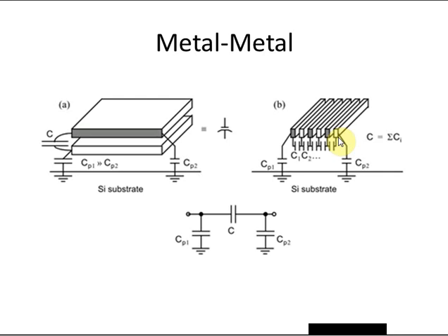We can make use of it in analog design by recognizing actually the sidewall capacitances obtained by jamming a bunch of these wires next to each other can be very high, and you can get a higher capacitance per unit area using a structure like this, it turns out, using the sidewall capacitances, than you can with two parallel plates like this. So of course if you want a two-terminal capacitor, you would just somehow short together alternating layers. And of course both these approaches, we can increase the capacitance density further by stacking these on multiple layers. A typical modern CMOS process might have 6 or 8 or even 10 layers of metallization above the substrate. So you could use 4 or 6 of those layers for capacitors if need be, and just stack these structures one on top of another and get a higher density.